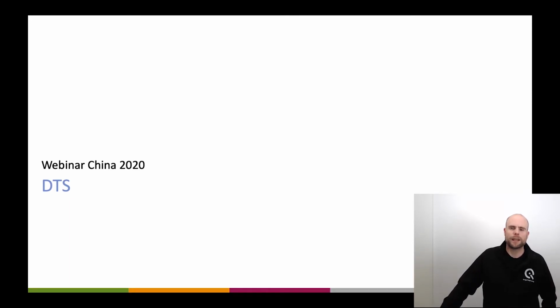The DTS, or Dynamic Test Stand, has a capability other than a static target like an OECF, dynamic range target, or color target, in that it can create the scene and change itself. So it's a computer controlled target for cameras that also allows to obtain new KPIs that are more sophisticated than traditional ones. So we do not measure SNR, but we measure CDP. And we can also measure MMP to describe how flickering light sources influence the performance. These are all KPIs that are rather newly developed, but have the big benefit that they can overcome the issues with traditional measurement.